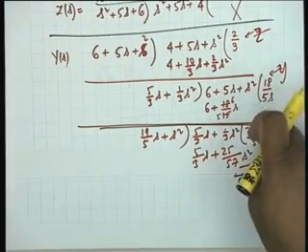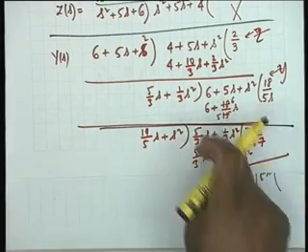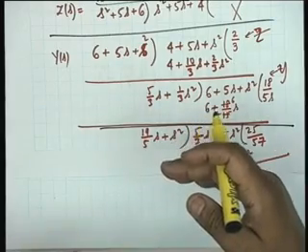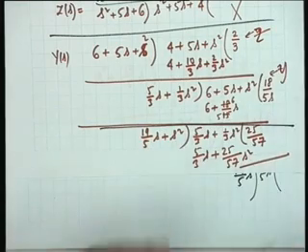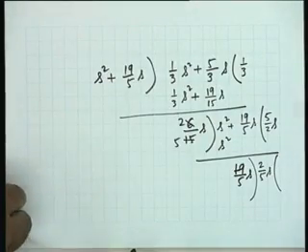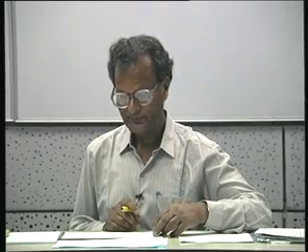The next one would not be an impedance, then it would be an admittance. Like we start dividing 19 by 5s by s squared, by this quantity. Yes, this is also possible. At some stage, you can go from lowest to highest or highest to lowest, or you can take the reciprocal and go. But as I said, it is purely trial and error. There is nothing that ensures that there exists a continued fraction. If it turned out positive or negative, we would have changed the powers again.